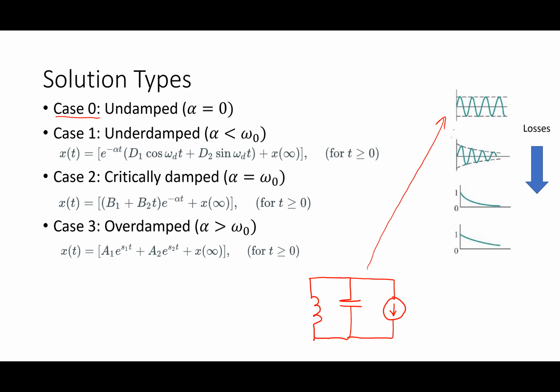So that would be called an LC circuit then? That would be an LC circuit, yeah. Now, in reality, there is no such thing as no losses, right? There are wires connecting components, so it's not possible to have no losses. But as you'll learn in later classes, I can do some special things with transistors to potentially overcome those losses and make it act like there are no losses. This particular circuit, for instance, I mentioned the other day, I might call an oscillator.